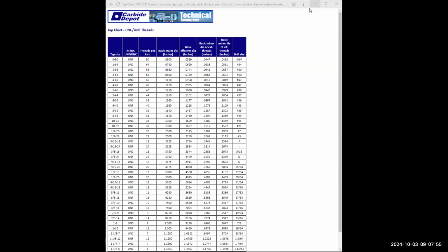Now I'm just going to assume that my drill has a 60-degree angle here. Okay, so I'm going to type in snap angle 30 degrees, and I'm going to go line. Look, I'm going to click right here, and I'm going to drag a line this way. Click, enter.